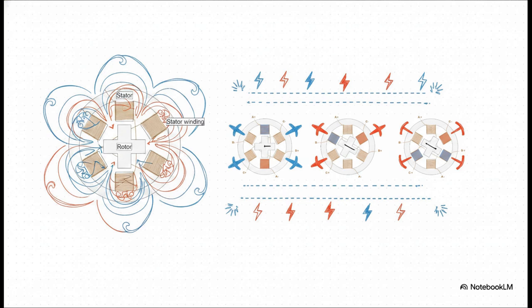To understand how it gets that kind of precision, we have to peek inside. Surrounding the stationary stator, there are teeth with coils wired around them. In the center is the rotor, which in this case is a variable reluctance iron core, and it's cut into a very specific, jagged shape. By changing exactly which coils on the outside are energized, we can force that iron core in the middle to physically snap into alignment with the newly created magnetic field.